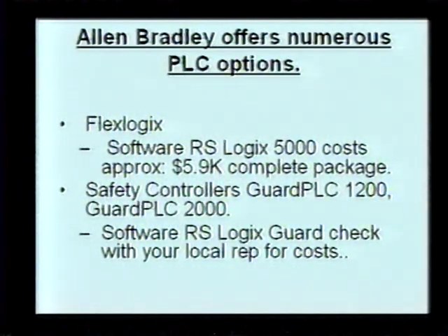But the important thing here is anything that can be used to cut, chop, or turn, or actually can cause a fatality, it can really kill a human being, is considered a safety issue, and it has to be controlled with safety PLCs, the Guard PLC 1200 and 2000. You can tell these are safety systems because they're orange. The ControlLogix PLC does have a safety integrity level of 2. That's how they base safety systems, so you have different safety integrity levels. You'll hear it as SIL levels, SIL 1, SIL 2, SIL 0. That is a safety integrity level.